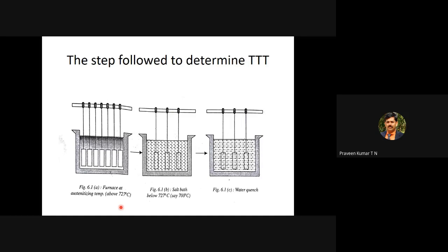That's a minimum requirement. Once you heat the steel above 727 degrees Celsius, we have alpha iron, which is also referred to as ferrite. Ferrite is transformed to austenite. Your eutectoid reaction takes place only if the temperature is above 727 degrees Celsius. The complete steel material should be at the austenitic temperature. It is also referred to as the austenitizing temperature. This is a transformation temperature.